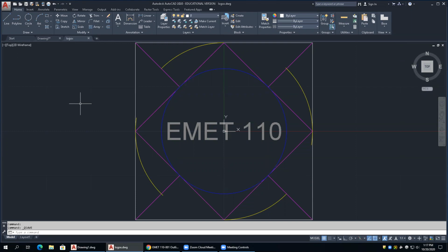What we can do now, you have a DWG file, you can bring another DWG file into a DWG file. So that's what insert will allow you to do. Besides inserting blocks, you can also insert DWG files into DWG files. Now, here's the thing to understand. When you bring a DWG file externally into a DWG file that exists, it takes all the stuff in the external drawing and it incorporates it into the other file. So if you have layer XYZ in the external file and 1, 2, 3 in the internal file, when you bring it in, you're going to have 1, 2, 3 and XYZ. Okay, so it incorporates them, right?